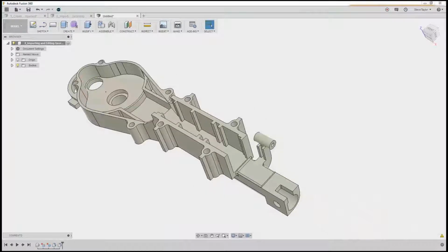Hopefully a lot of this is, pardon me, getting a feel for the actual tool itself and how it works. If I move to the front end of the model, I want to get rid of this notch in this face, this little notch here. If I was just to click that face and press delete, you'll notice it actually deletes the whole thing, which I didn't want. Yep. I'll lose a lot of geometry.